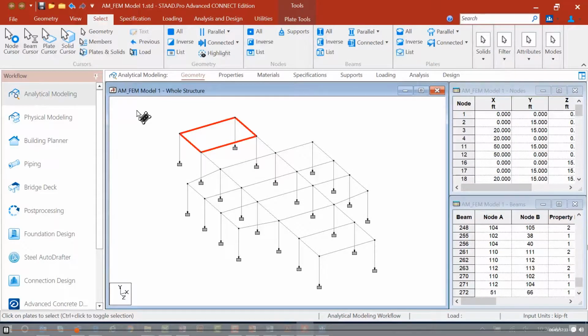Now, as I mentioned earlier, we're never going to typically just create one single element in a particular bay. If I take a look at this slab element, we'll call it for now, it is actually only connected to the top of the columns. Currently, there's no connectivity with the supporting beams, which should also be sharing stiffness with that slab element. It should also be sharing loads with that slab element. So for those reasons and for others, we're going to create a mesh from this element.